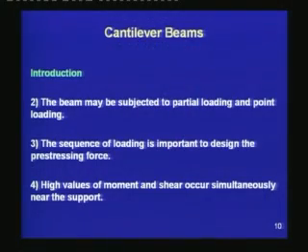backspan under service loads. The second aspect is the beam may be subjected to partial loading and point loading. A cantilever beam, if it is subjected to a partial loading or a point loading, can generate a different type of moment condition as compared to when the load is distributed throughout. Hence, a partial loading or a point loading analysis becomes important for a cantilever.